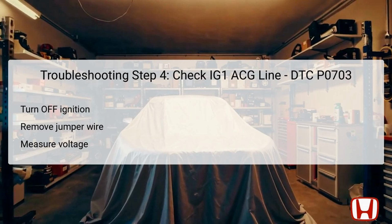Test point 1 is located at pin 4 of the brake pedal position switch 4P connector, and test point 2 is the body ground. This step is crucial as you're checking for the presence of battery voltage in the system. If you find battery voltage at this junction, it indicates that the IG1 ACG wire is functioning properly, allowing you to proceed to Step 5. If there isn't any voltage, you must investigate further in Step 6.